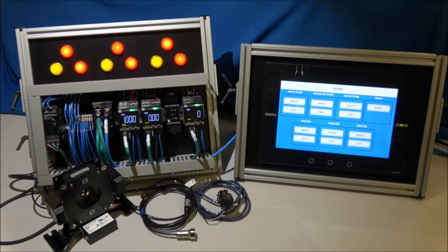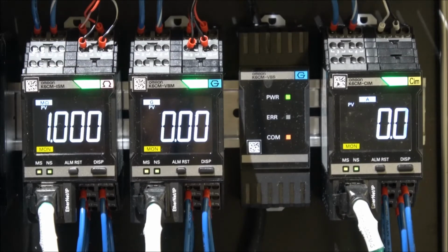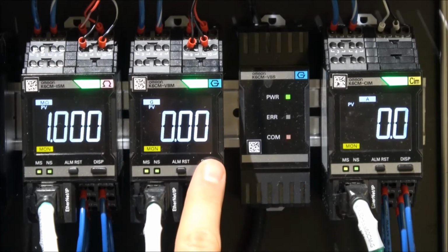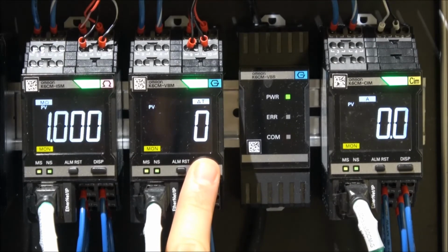Now I will go into more detail on the local display of the K6CM as well as the HMI screens that we have developed. Here we are showing the local displays for each K6CM. You can see the variables that each K6CM sensor is monitoring locally on the display. For the insulation resistance, you see mega ohms and milliamps. For vibration and temperature, you see G's of acceleration, velocity, temperature, and then delta temperature between the motor and the